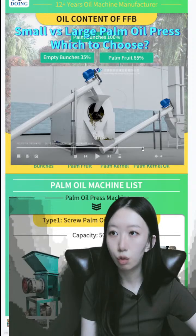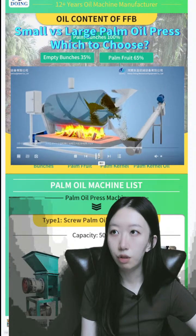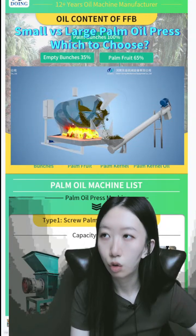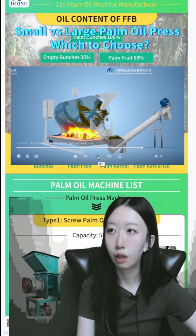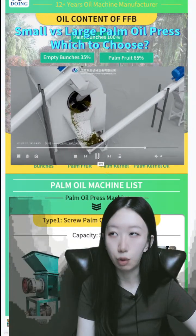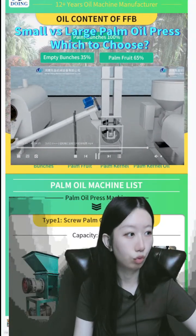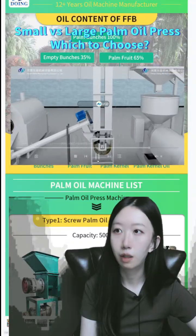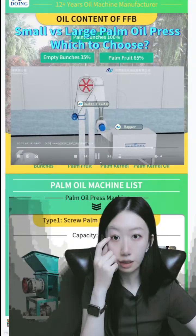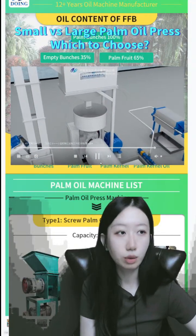Next, this is a cooker. After crushing, the palm kernel is transported into the cooker to adjust internal moisture and temperature, making it fit for pressing. Next is pressing. During pressing, we use a presser that is a palm kernel specific presser.